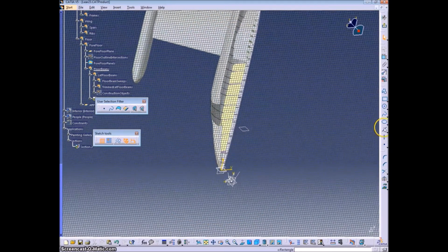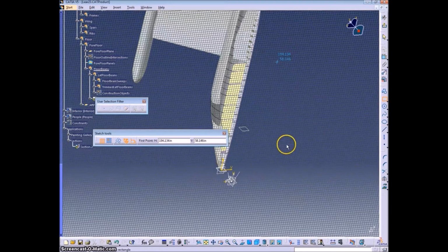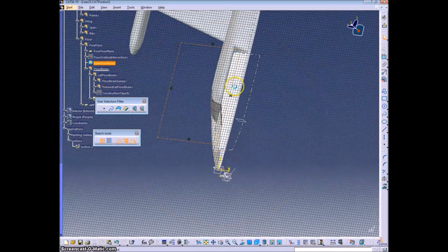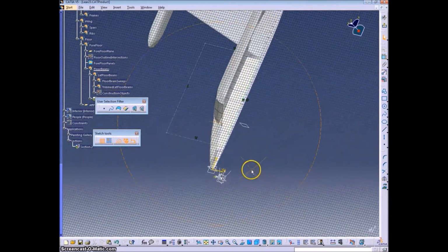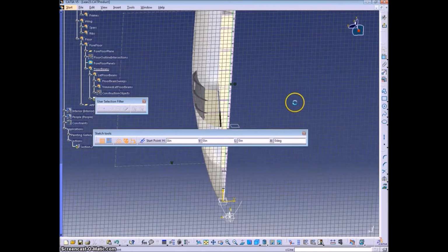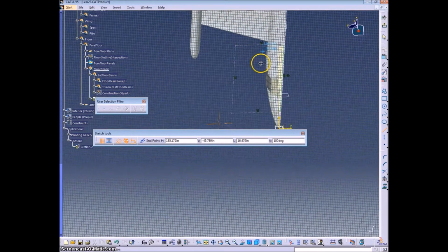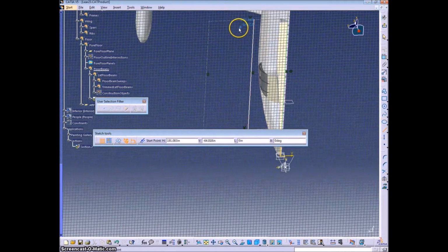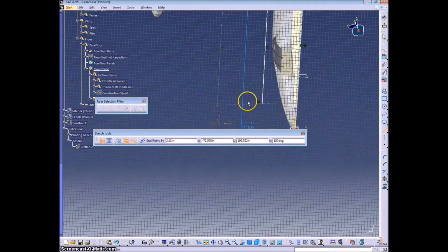And now to add the longitudinal floor beams. Same principle as the many times before, where we just draw lines as guides. Here I just have a square that I constrained to the floor panel plane so that the edges are in the correct spot. The fore and aft edges.